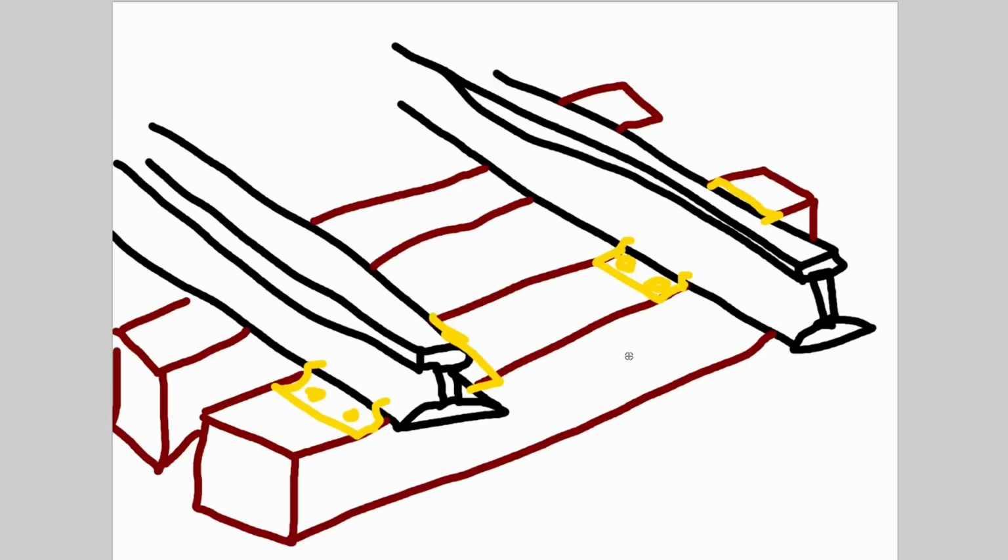One important detail to note about the ties that also helps with these tie plates is that typically the ties are treated with a special coating called creosote, and creosote is basically a coal tar that acts as a preservative for the tie to make it last longer in harsh environments. As well, it also acts as a lubricant so that as trains run over, there's less friction and wear into the actual tie surface from any motion or any vibration of the rail and tie plate itself. Obviously, the tie plate gives a larger area, which helps limit the wear, but adding that creosote also allows for any motion that does happen to affect the tie even less, which results in less maintenance.